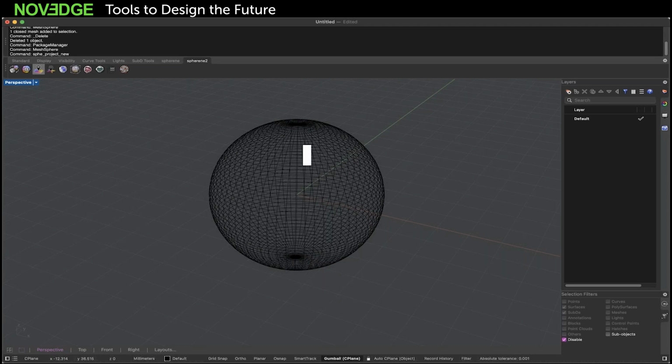So you are guided with tooltips while you're working. So this generates a project. That's the layer with the project name. It contains a mesh, the so-called envelope, and it contains a field, a density field. That is this number. This number means the result will have the volume of 95% of that volume.